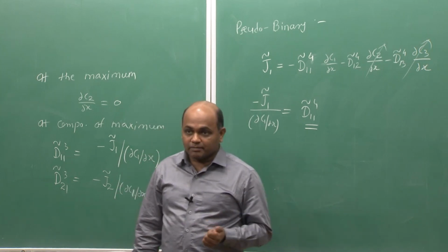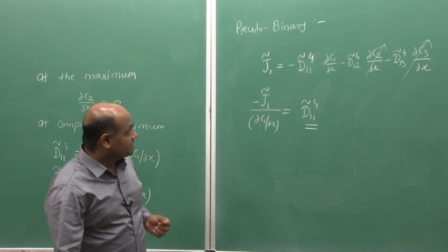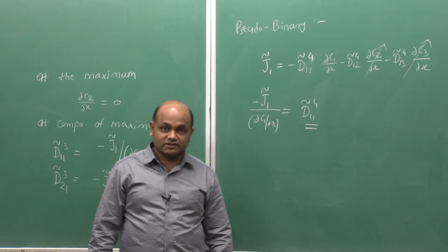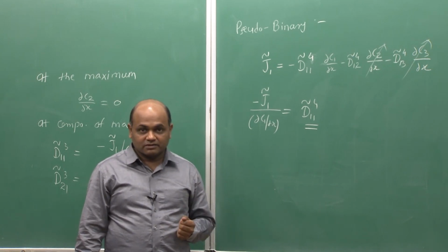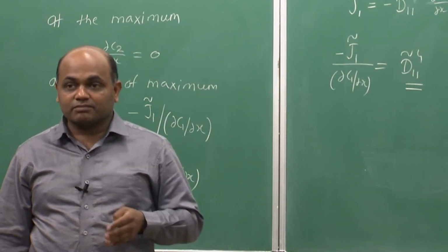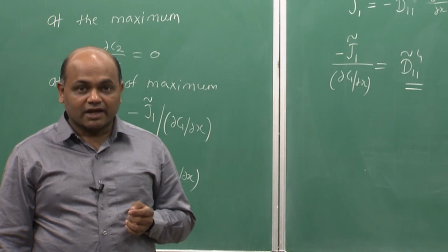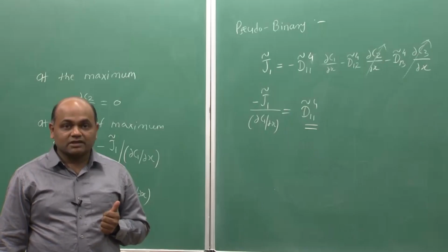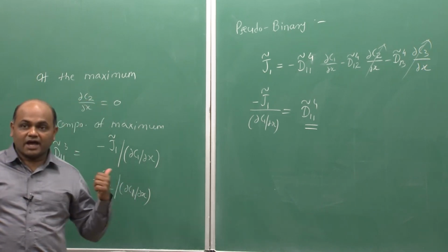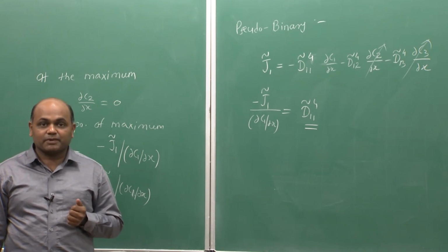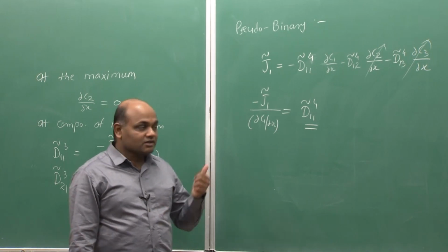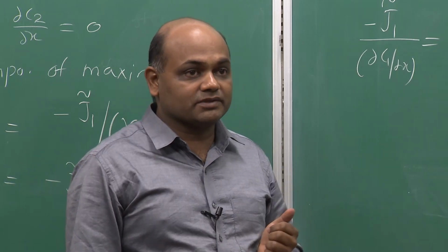Similarly, a pseudo ternary approach has also been proposed, in which instead of 2 here we will have 3 varying concentrations and remaining constant. And if we can design 2 such couples with the same set of components being invariant and having at least one common composition in the diffusion zones of the 2 couples, similar to the Kirkcaldy's approach for ternary that I explained, we can solve the 4 equations at the common composition and get 4 independent interdiffusion coefficients.